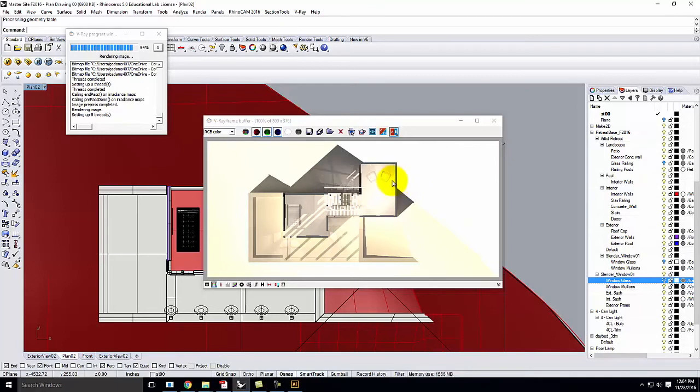There's probably a few things that I need to touch up. I should change the material of the section cut to be like a black or something so we can see what's been cut through. I probably also need to adjust some of the exposures. It looks like it's a little bit light, and so I'm not quite seeing everything that I want to see. Some of the light that's being cast out is coming from the lights that are inside the building. So probably my exposure needs to be adjusted a little bit as well.